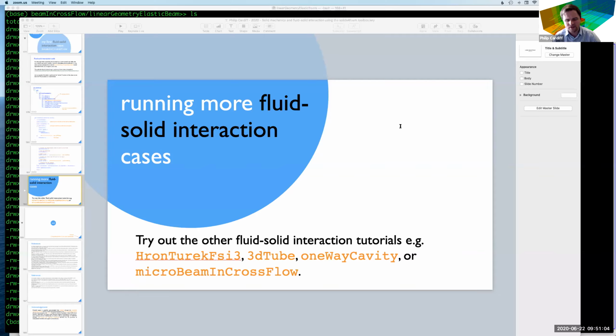Probably at the moment, if you have very thin geometry, so if you try the hygrothermal test case, it's really, really slow. Because of the way the standard segregated solver in OpenFOAM works, if you have very thin geometry in solids, it's very slow and inefficient to use a segregated solver. So a block coupled solver, I did work on that, implemented and shared it for small strains, and it works really fast, but not for large deformations like in the hygrothermal case.